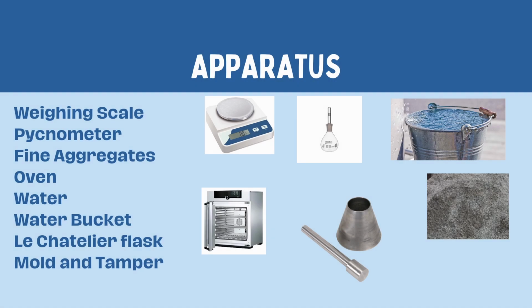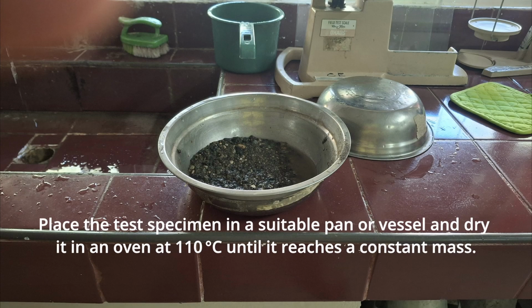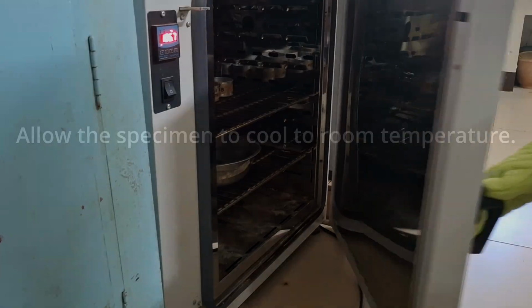The apparatus are weighing scales, pycnometer, fine aggregates, oven, water bucket, Le Chatelier flask, mold, and the tamper. Procedure: drying the test specimen. Place the test specimen in a suitable pan or vessel and dry it in an oven at 110 degrees until it reaches a constant mass. After drying, allow the specimen to cool to room temperature.